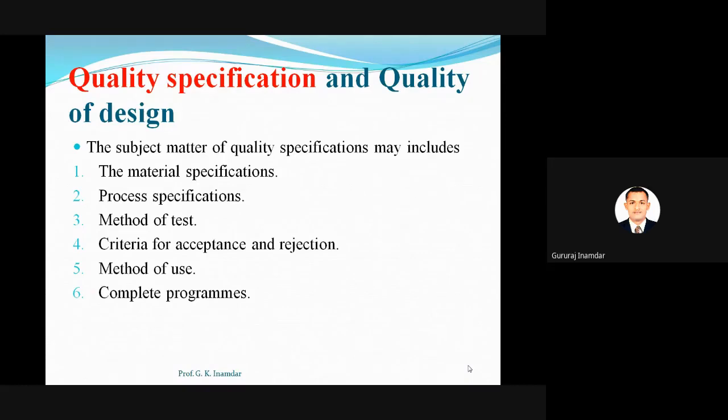So if you consider mass production is required, for example, nut and bolt manufacturing, what is the acceptance and rejection process? You might have studied it in a number of subjects: go gauge, no-go gauge. I think we have already discussed that type in the curriculum.